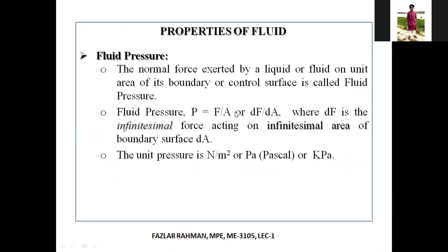So can you tell us some factors that cavitation is dependent on? For example, if the fluid is denser, how many bubbles will it create? Well, it depends. A lot of factors are involved there. Fluid has viscosity, capillarity, and a boiling point. What is the boiling point of the liquid? How much pressure is there? What is the viscosity? There are a lot of factors. In cavitation, you can do a PhD on cavitation, on how you can prevent the cavitation in the fluid system.